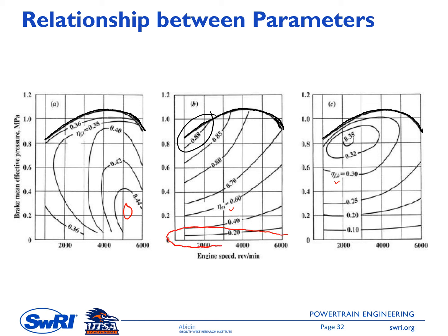If we go to the idle condition, it means there is no power output by the engine, and then the mechanical efficiency is 0. On the far right side is the map for the engine brake efficiency. It has a maximum around this island. This one is just the multiplication between the engine indicated efficiency and the engine mechanical efficiency.